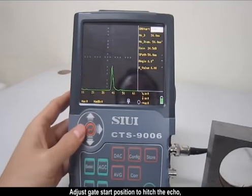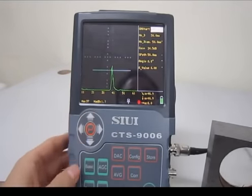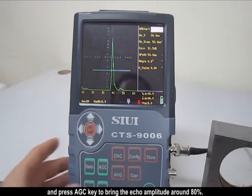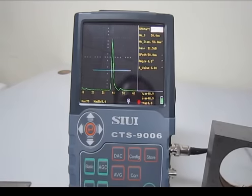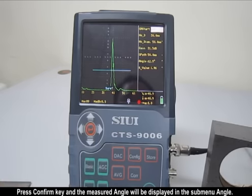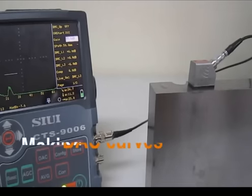Adjust gate start position to hit the echo, and press AGC key to bring the echo amplitude around 80%. Press Confirm key and the measured angle will be displayed in the submenu Angle.